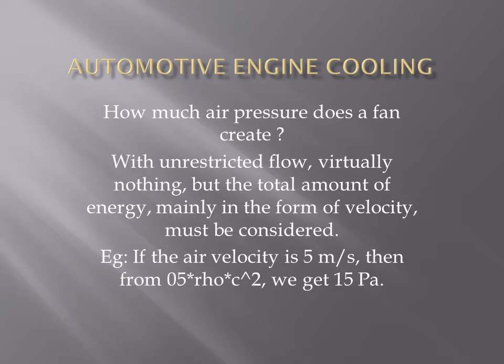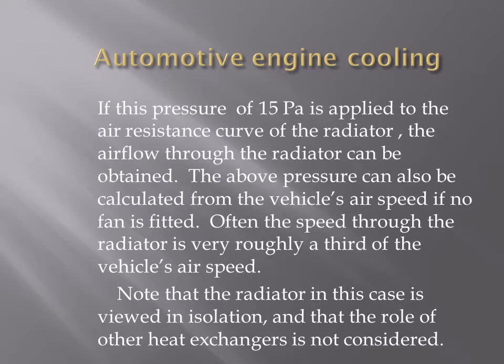How much air pressure does a fan create? With unrestricted flow, virtually nothing. But the total amount of energy, mainly in the form of velocity, must be considered. Example: if the air velocity is 5 meters per second, then from half rho c squared we get 15 Pascal. Rho's value is of course 1.2 at the coast.